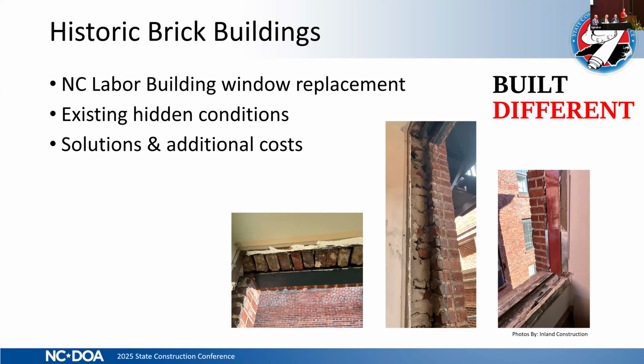The lintel only supports the first width of exterior bricks, rather than, as assumed, being across the top of the window as well. Header bricks either sit directly on top of the existing window, or they're arched over the window. Non-waterproof elements in the window or in the wall were completely deteriorated beyond repair or reuse. So what this means is that the framing materials that were used to support the windows are no longer actually supporting the window. These windows are basically held in place by caulk.